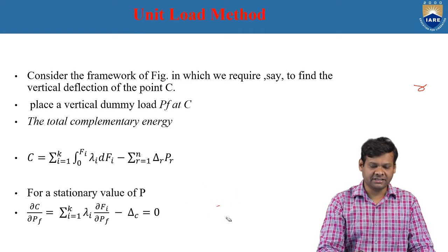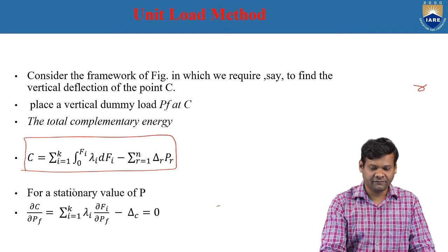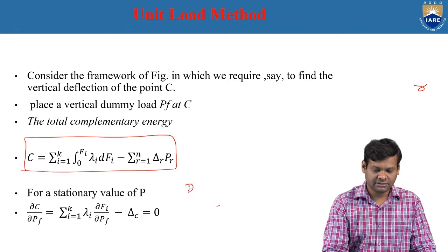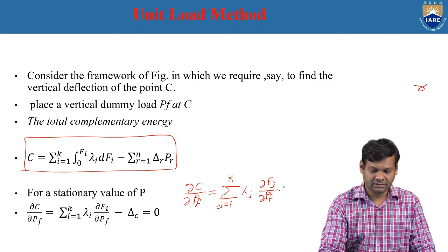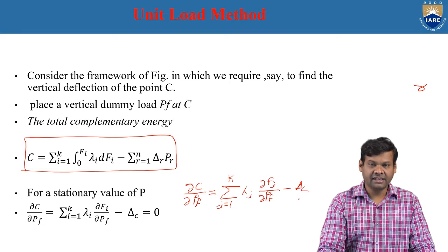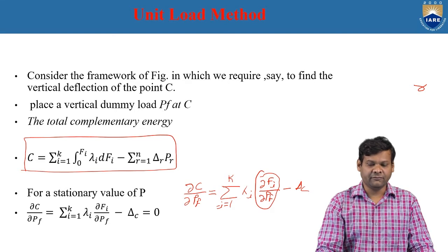When I differentiate this complementary energy with respect to some load P_F, I get dou C by dou P_F equal to sigma i equal to 1 to k, lambda_i dou F_i by dou P_F, minus delta_C.